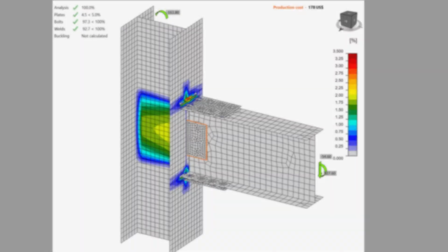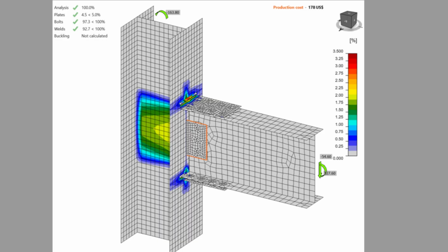In simple terms, inelastic analysis recognizes that steel doesn't behave perfectly elastically all the way up to failure. It does this by explicitly modeling yielding, and importantly, efficient inelastic analysis enables the powerful method of connection design implemented in IDEA StatiCa.